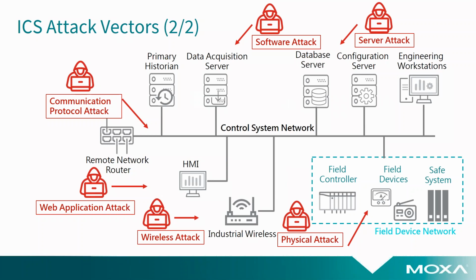So you're going to see default passwords that have been around for 10 to 15 years, vulnerabilities in the system, and fairly simple passwords like 1, 2, 3 or "password" to gain access to the field device. So it's not just on the IT side, but also on the operational technology environment, the ICS side. We do see many attack vectors that we have to be aware of, and we need to make sure that we secure those attack vectors.